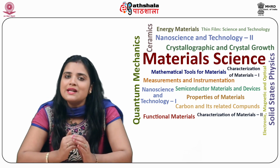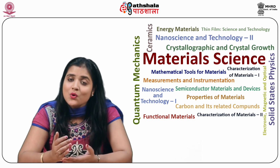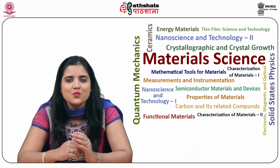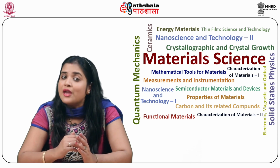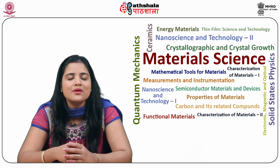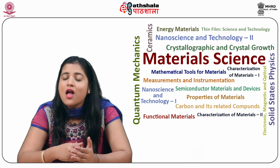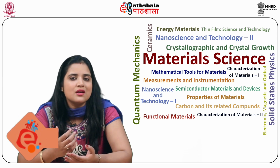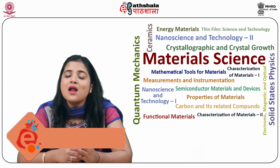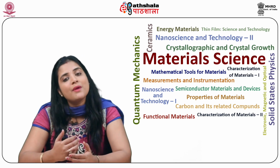So students, let us now summarize what we have learned in this module. In this module, the concept of digital to analog and analog to digital conversion was explained. Then, the digital to analog conversion using variable resistor networks was explained. The expression for analog output voltage obtained using the variable resistor method was derived. Finally, the binary ladder or R2R ladder for digital to analog conversion was discussed and the expression of gain was obtained.